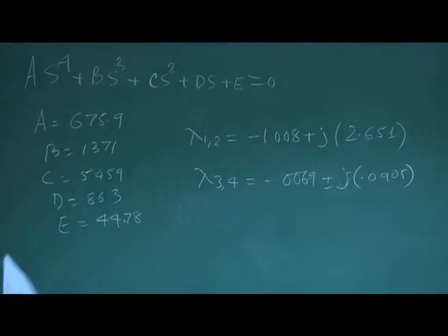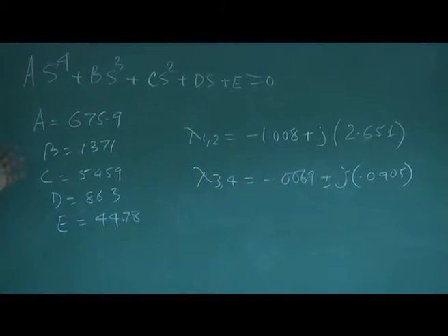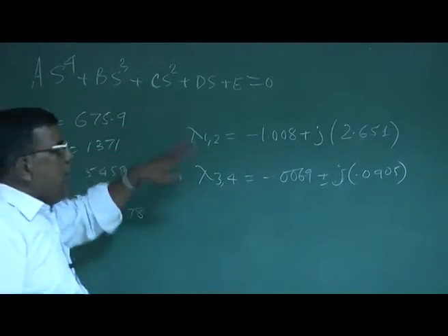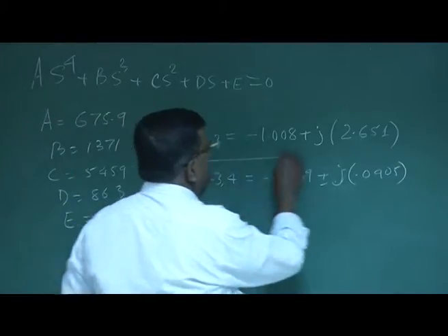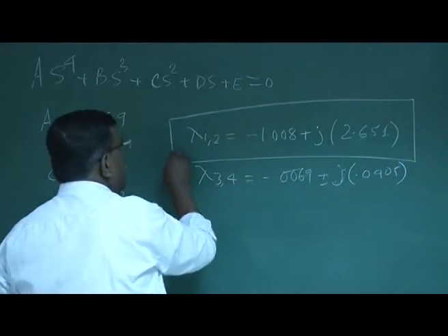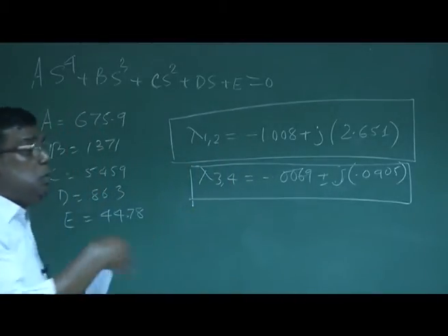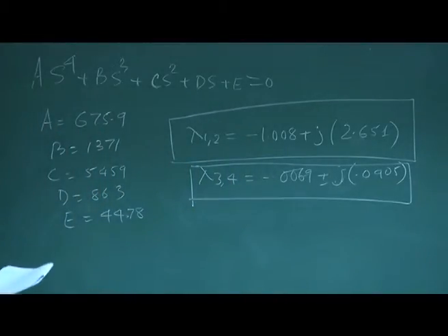Typically, you'll find for most business jet airplanes, if you get those aerodynamic coefficients and solve this equation, the roots will get segregated into this: one pair here, one pair here. So, two second order system behavior. That's the beauty of longitudinal dynamics.